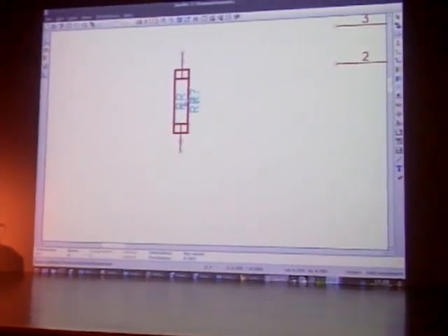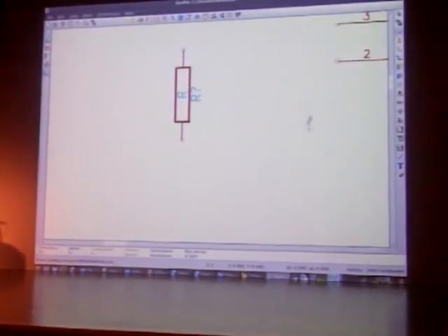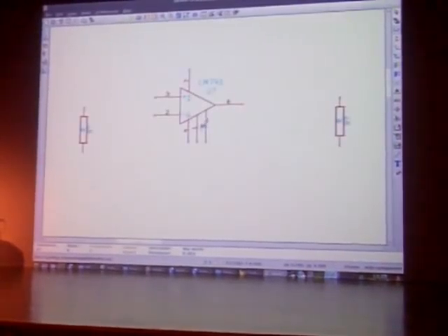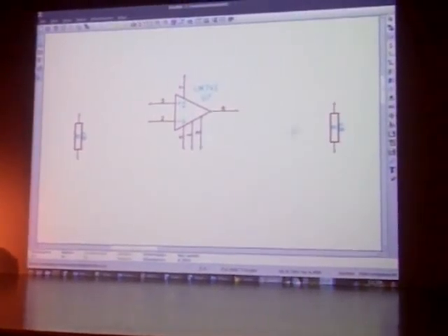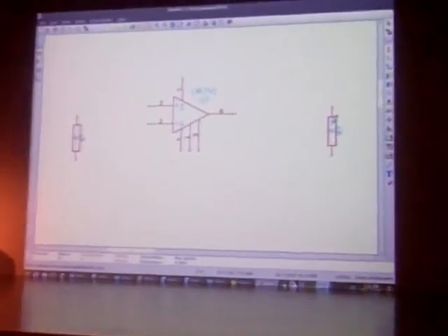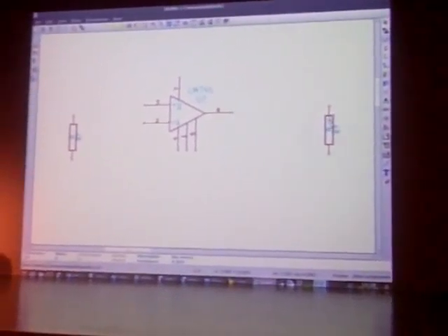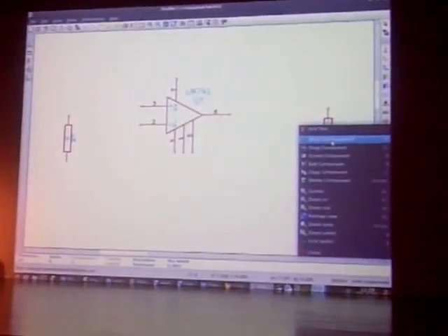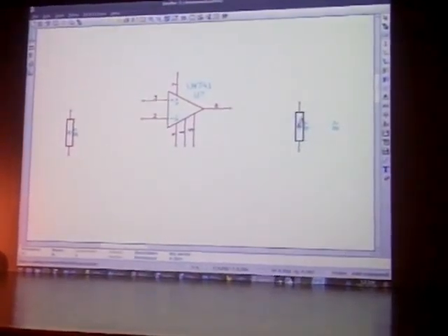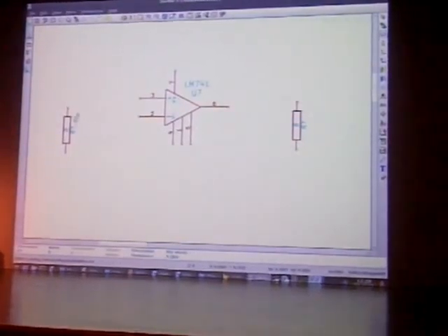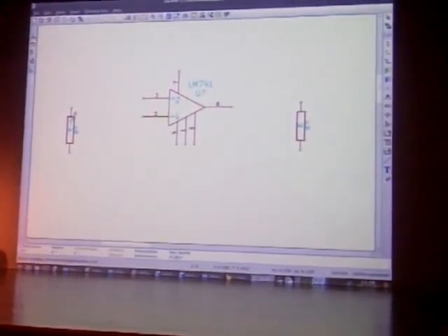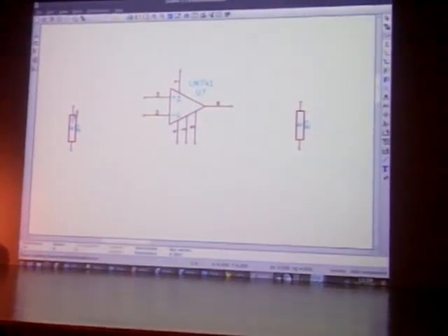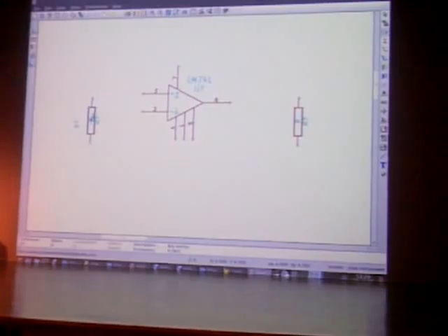Okay, what I've got here is actually two of them. So I'm just going to undo. All right. So I've got two resistors moving. You can do it the long way: right-click, select, move, and move. Or you can do it the short way, which is to mouse over the part you want to move and just type M, the M key. That'll get you to move the part.